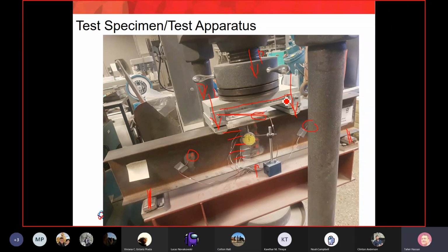Okay, last piece, and then we move to the test. This guy here, you see this gauge here? There is a gauge here, and the gauge is connected to the underside of your beam. What this does is simply, when we apply load, we know that our beam will deflect down under the load. However, because the beam is so strong and the span is so short, we cannot measure or see this with our bare eye. It's very little, probably a fraction of a millimeter or maybe a millimeter, which is very hard to see.